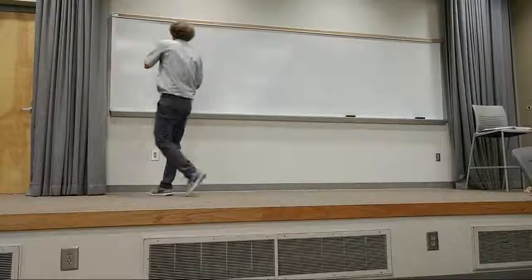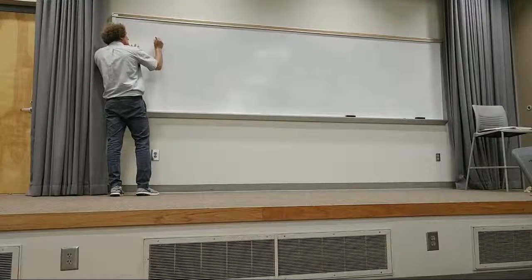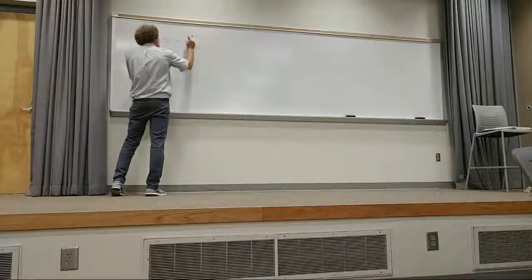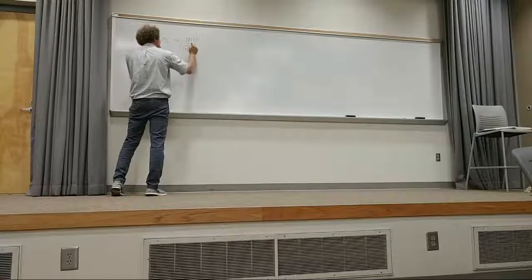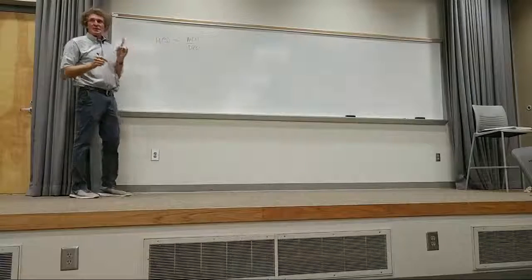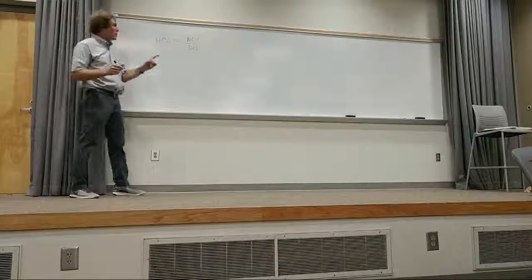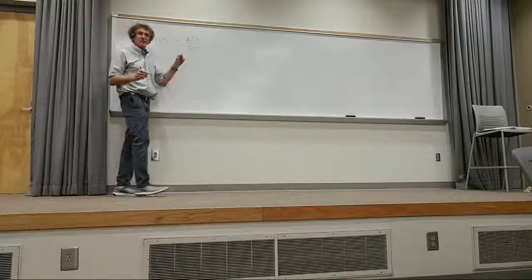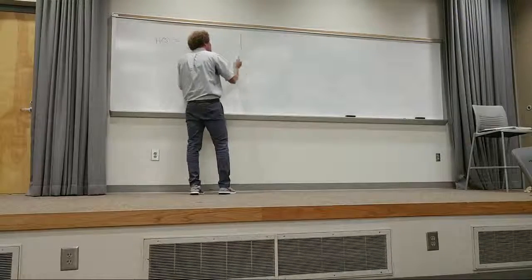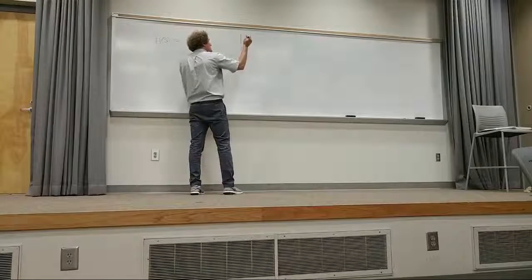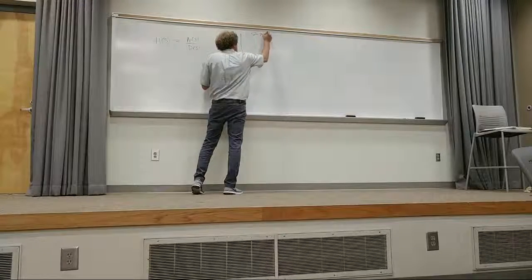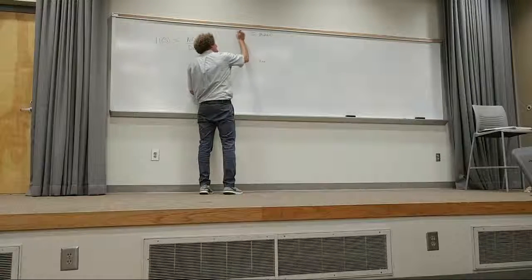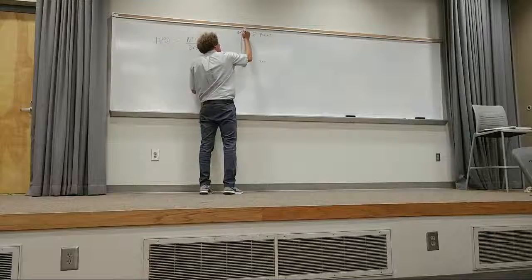If you had a function, some transfer function, H of s, equal to some numerator, N of s, divided by some denominator, D of s, I said one thing. For stability, the poles had to be in what? The left-hand plane, correct? Strict left-hand plane. I'm just going to mention this one more time. When we talk about the S-plane, this is always the real part of S, and this is the imaginary part, or the J part.